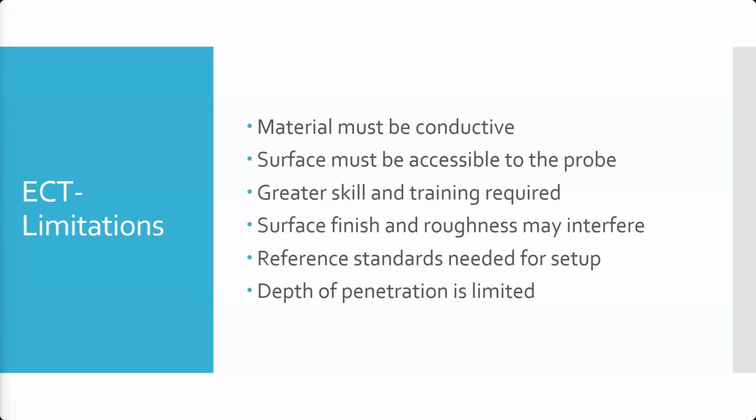Just a little bit of movement in your probe in relation to the surface is going to cause some kind of indication. You have to have reference standards before you start. That means you have to have something to compare it against.